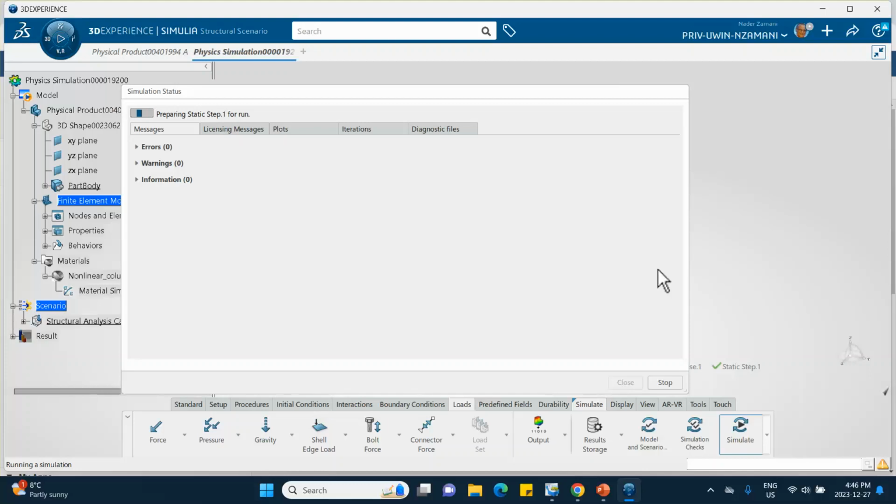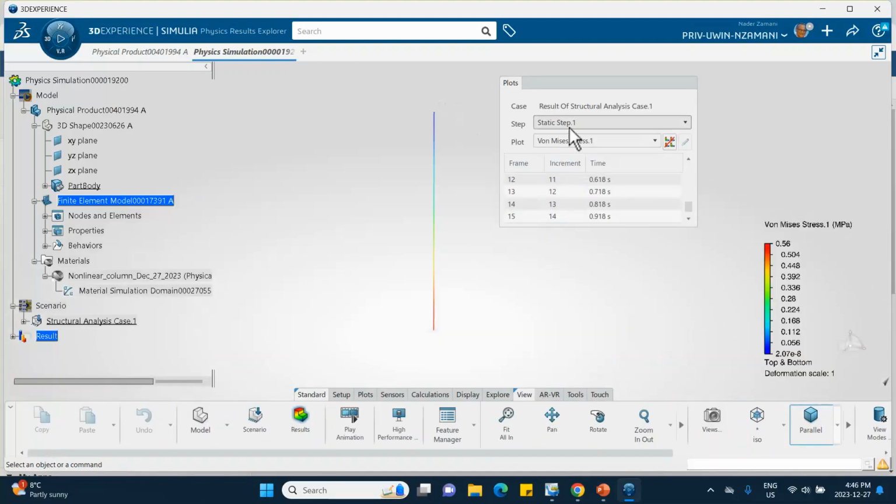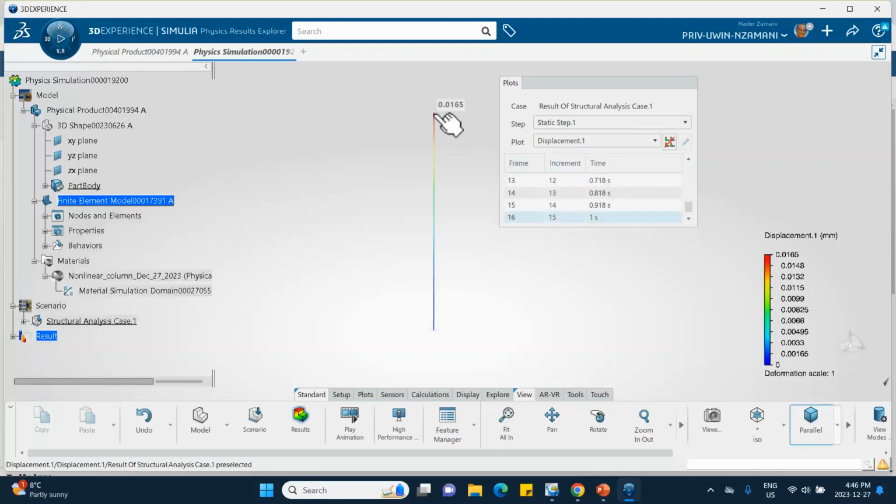Now, when you try to show the bending or displacement of the beam, you won't see anything. And the reason is that because you said this geometric nonlinear effect is on, the default scale factor becomes 1. And this is a tiny force. For visual purposes, you won't be able to see. If I close it, you see that? Let me go to displacement. The biggest displacement at the top is 0.001 millimeter.